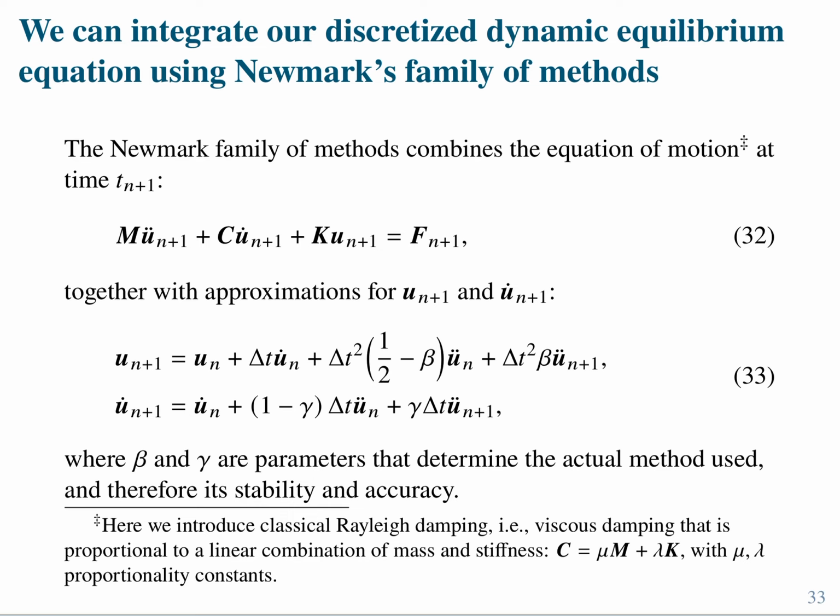we're going to discuss these two equations here. Some people call this a beta-gamma method. It's actually Newmark's family of methods. And it is indeed a family of methods and not only one method, because depending on your choices of beta and gamma parameters, you obtain a concrete method that perhaps was published earlier by someone else. Indeed, Newmark was really a generalization of different time integrators that led to different approaches, right?